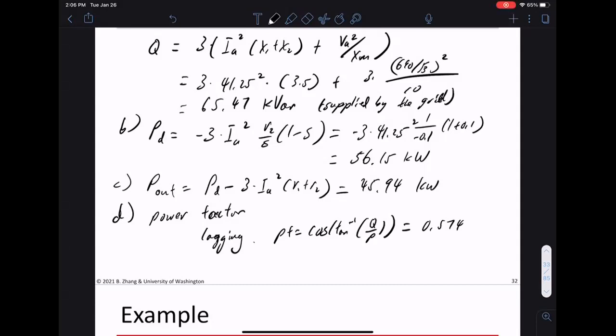Because the type 1 turbine also consumes reactive power, and if your load also consumes reactive power, you actually cannot directly just connect the turbine to the load. They're both consuming reactive power. You need to get reactive power from somewhere. So that's why type 1 turbines are not the best in a standalone system, because somebody needs to provide Q. There's no Q in the system. So yeah, go ahead. Would it be possible to have one of these in a standalone system?